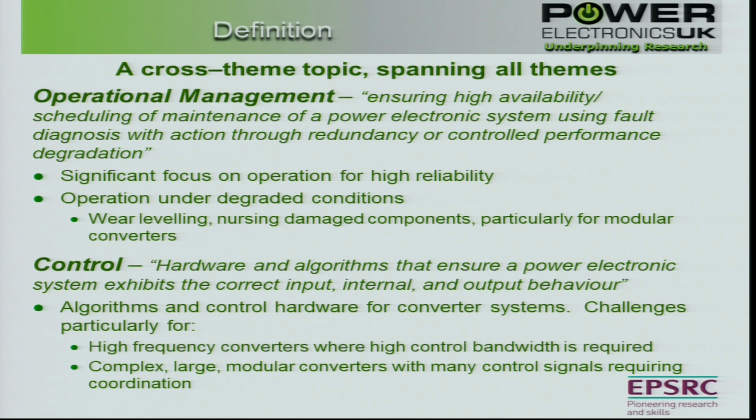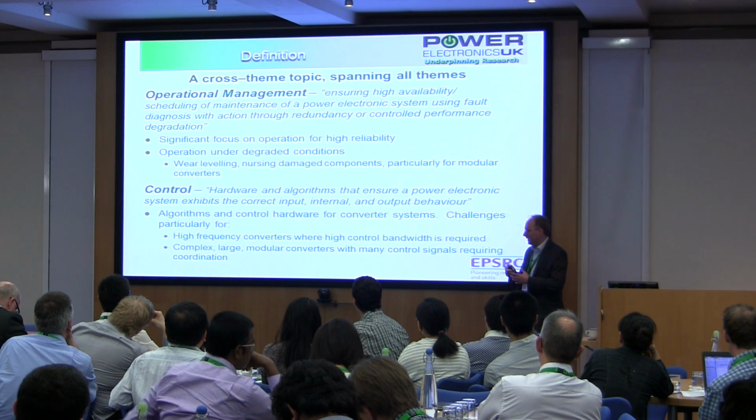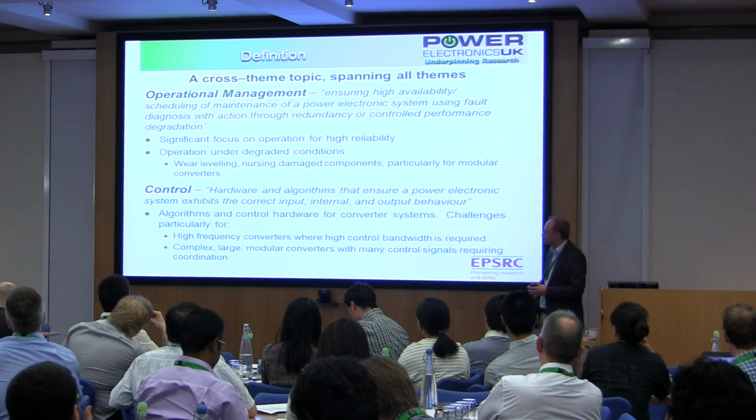So first of all, what do we mean by this as a title for a cross-theme topic? Well, the control aspect, of course, is something that, as power electronics people, we're all very well used to dealing with, where in terms of standard control, we think about controlling the input, internal behavior and the output behavior of a converter, or perhaps a drive system, for instance. The aspects to do with the regular functioning of a converter, as far as we're concerned in the center, the challenges there really occur when we start to go to high frequency, and we then have relatively small amounts of stored energy in a converter as our passive components shrink in size.